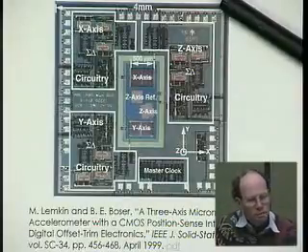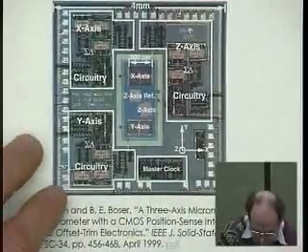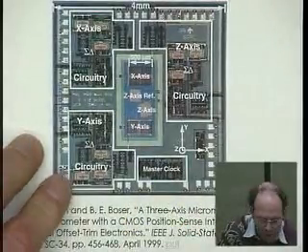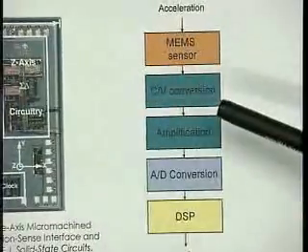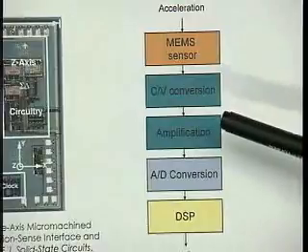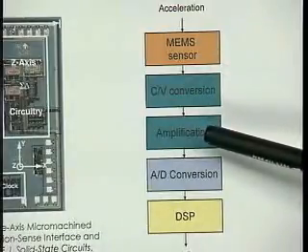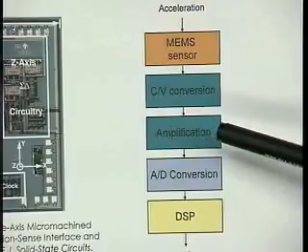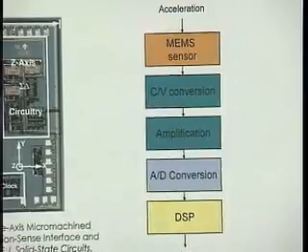Extremely small motion. Okay? And of course, the trick is to build very sensitive analog circuits that take capacitance and convert that into voltage without introducing errors. An important consideration here is going to be noise, and we're going to talk a lot about noise, because noise, it turns out, has a lot to do not only with the performance of a circuit, but also with how much power, for example, it dissipates, how big it has to be, and all sorts of other interesting things.